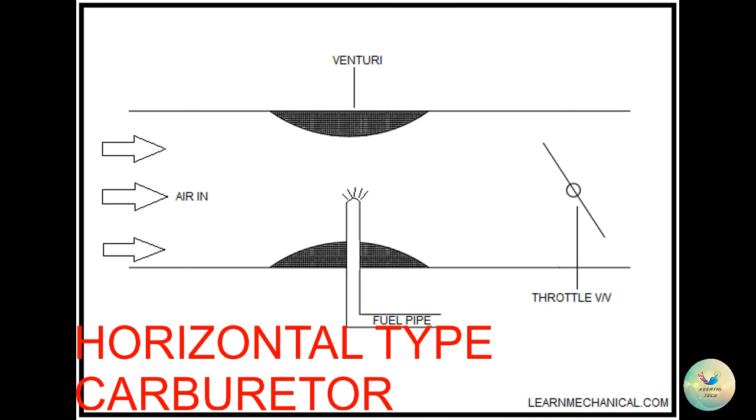place. Horizontal type carburetor. When you rotate the downdraft carburetor in the horizontal direction, then it becomes a horizontal type carburetor. The working principle of this type of carburetor is very simple. Here the carburetor stays in the horizontal position where the air is coming in through one end of the carburetor shown in the below figure, and mixing with fuel to make the air-fuel mixture, and then the air-fuel mixture is going to the engine cylinder for combustion.